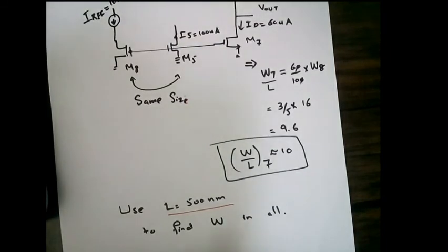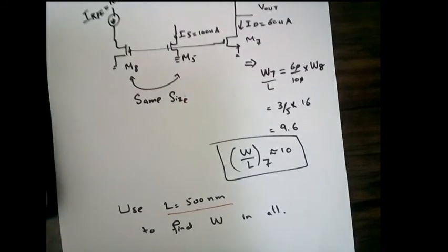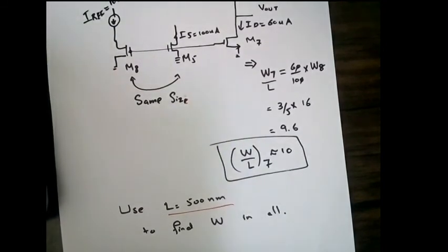One thing we didn't insert at this moment was the compensation resistor. If you want to add the compensation resistor, you can add it and tweak things accordingly. But this is the normal design process. If you have any amplifier, not a two-stage but any different type, you can do the same thing based on the provided specifications. The provided specifications will be similar in all designs.